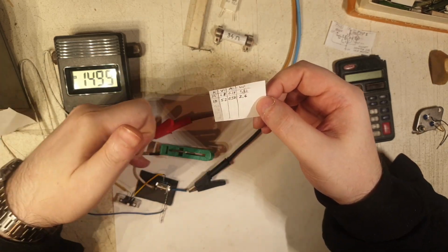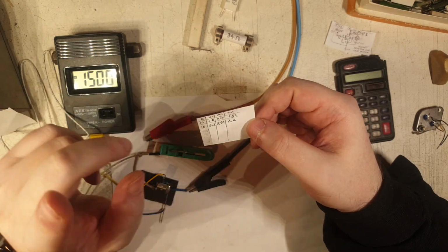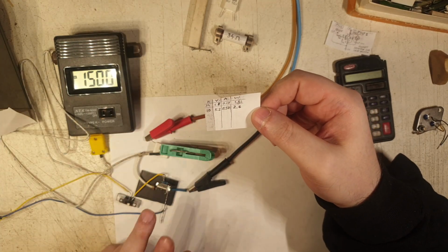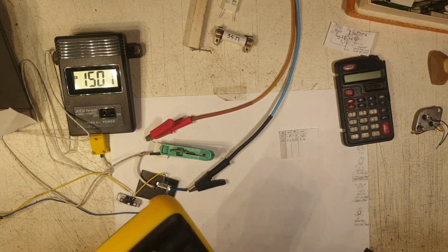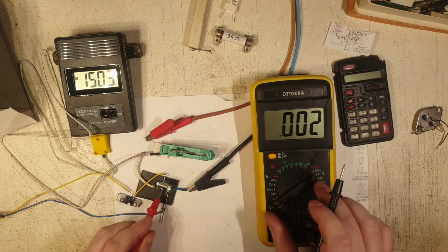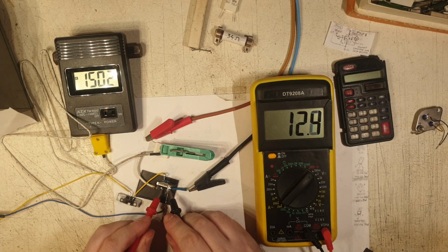I should actually take the data from the MOSFET, the voltage and the amperage through it. Well, the amperage is the same, it's 0.5. But I should get the voltage over the drain and source of the MOSFET and calculate the actual wattage over the MOSFET. And I can do it right now, because I'm taking the voltage over it. So right now I'm here at 2 volts. Let's see. Yeah, I should go to 200 millivolts, and I'm getting 12.5 millivolts.